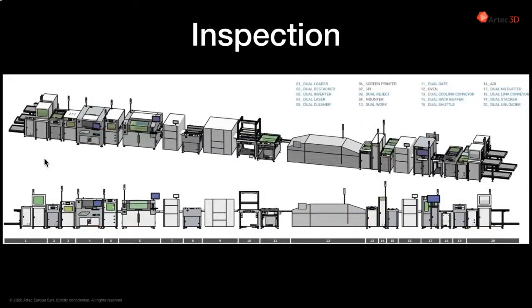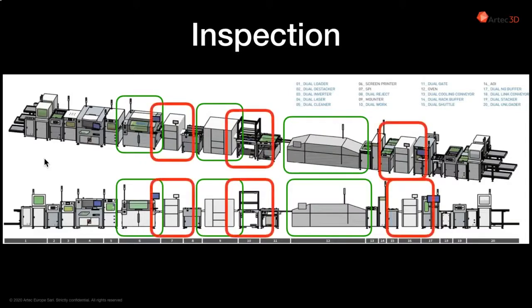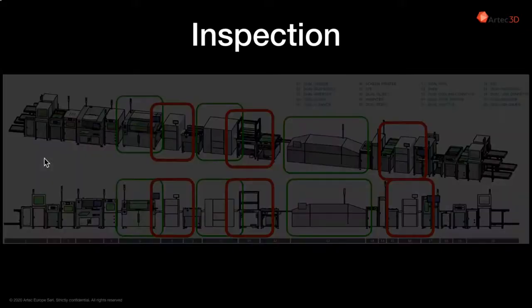So we've considered 3 stages of the line, and the minimal line without any inspection. I never recommend you to do that without any inspection. Let's see what we should inspect after each stage. First of all, we should inspect the solder paste, how it's applied.